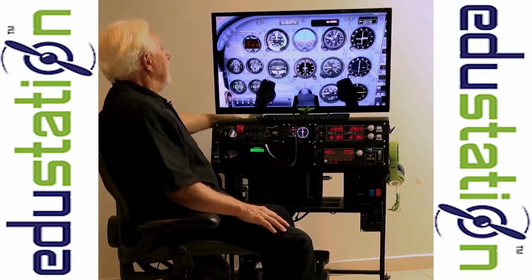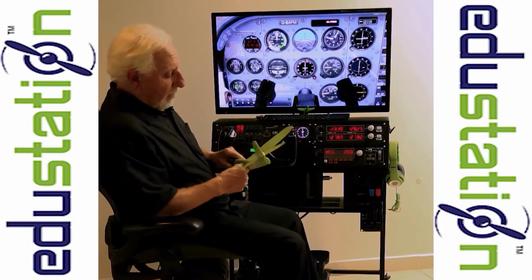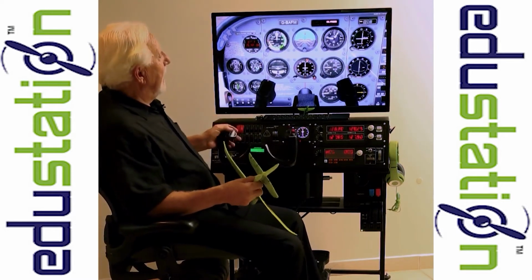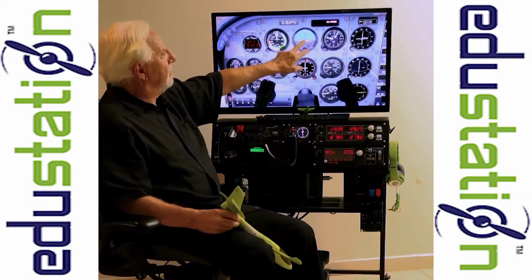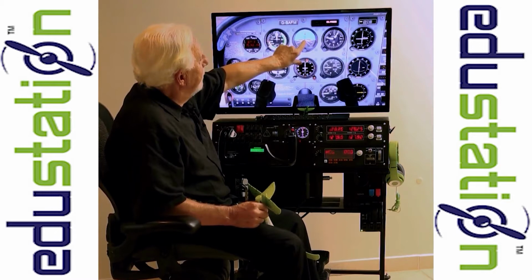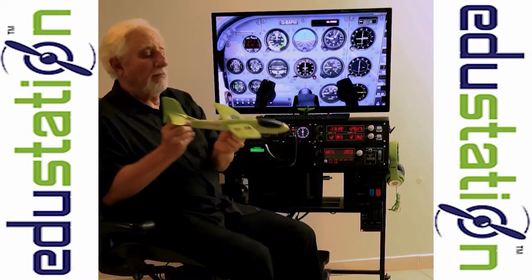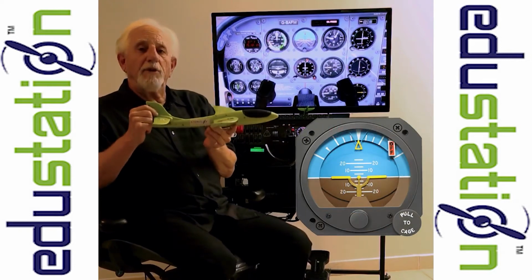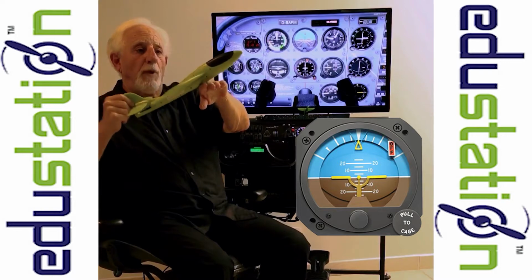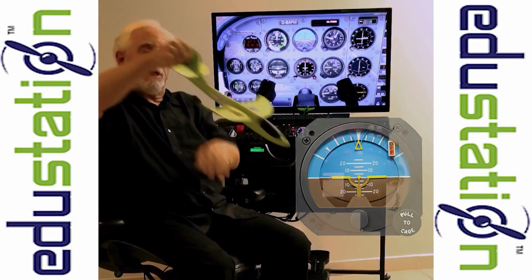And I teach this to lots of kids, and I usually get their video game brain to kick in so that they test up and down and left and right, and by the time they understand that, they're able to fly straight and level. You'll notice above the white line are 4 black lines. In this airplane, they represent 5 degrees of angle of attack. So level, 5, 10, 15, 20, pitch up. 5, 10, 15, 20, pitch down.